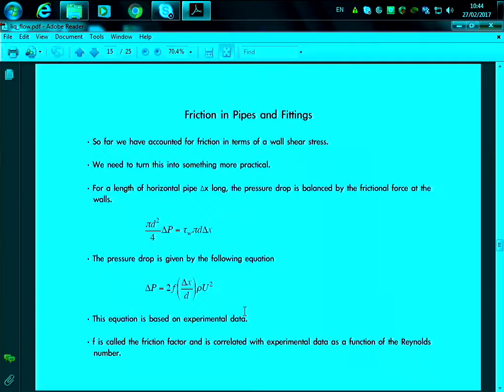On page 11 you have the Fanning friction factor chart. Whenever you don't know what type of F is provided by the chart you are looking at, you always have to look at the laminar region. The laminar region is always a nice straight, inclined line. It doesn't change a lot.